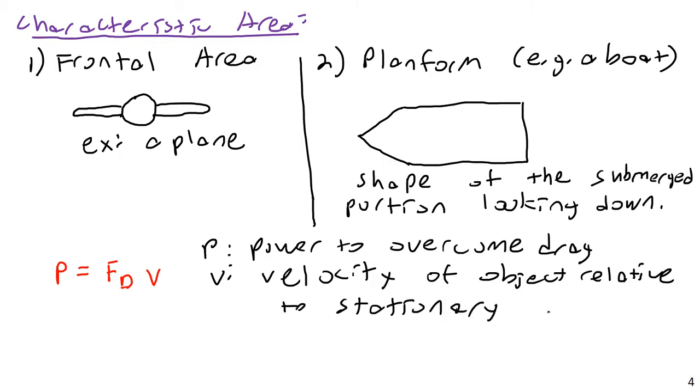So this is the one case where you absolutely do have to use the absolute velocity rather than the relative velocity. The relative velocity that we mentioned previously is the velocity of the fluid relative to the object that it is exerting forces on. In that case, you're always going to want to use U, the relative velocity. You use that for calculating your Reynolds number, and you use that for calculating your drag force, Fd.